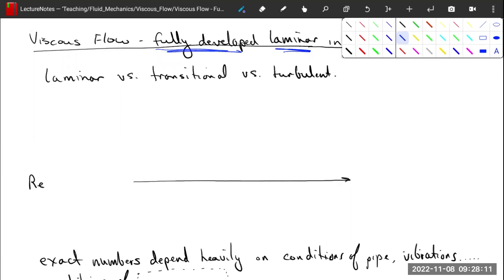pipes. So we've talked about this several times, the transition between laminar flow, which is steady state, smooth, right, dominated by viscous forces, into transitional flow where inertial forces start to become more significant and they produce some momentary instances of chaotic flow, and as that transitional flow becomes fully turbulent. And all this transition in this direction is a result of Reynolds number, which is equal to rho v d over mu, increasing, right? As it increases, we see this transition from laminar to transitional to turbulent.